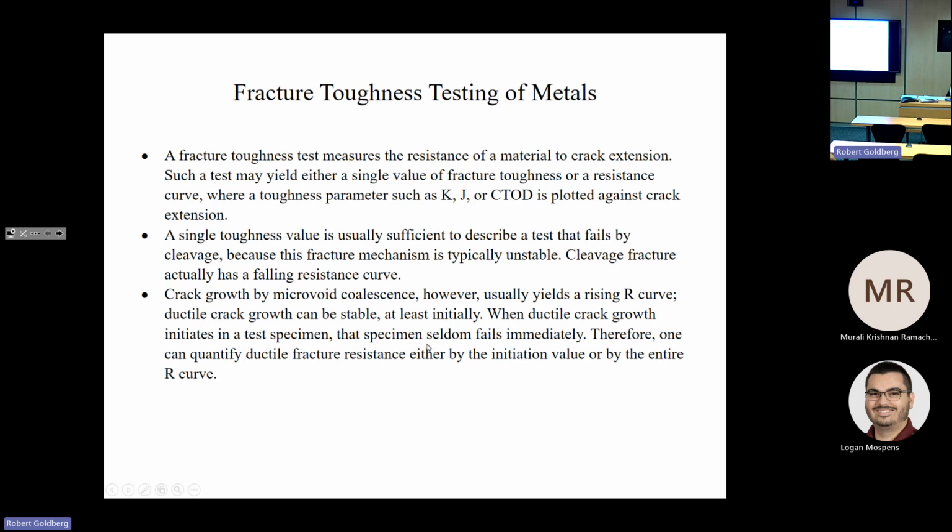The equivalent in a deformation analysis: sometimes you'll use the yield stress as the design criterion. As soon as your structure yields, you'll call it a day and say that it's outside of the bounds of your application. Or in other applications or loading conditions, it's okay that you have yield and it's still usable as a structure, you're allowed to accommodate plastic flow, and you keep on using the structure, and you design not for the yield stress but for the ultimate stress.